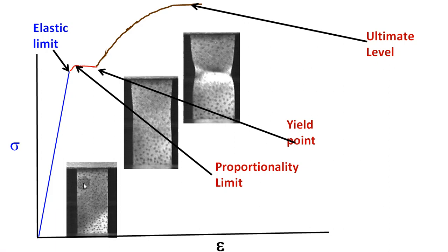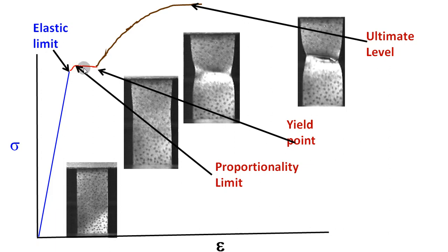And if you project this point and this point, you can notice some kind of a plateau, and the stress is constant. At this particular point of time, particularly in ductile materials, I hasten to add this, you will notice a large deformation, and this point is called the yield point, and the corresponding stress is called the yield stress. And here you will see a noticeable, local kind of necking, look at a weak point.